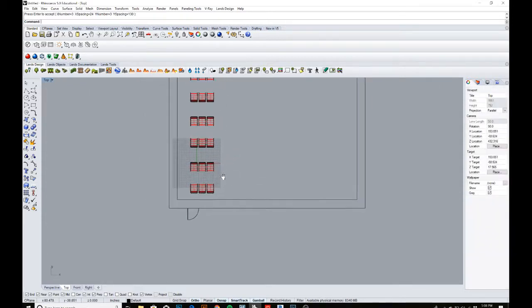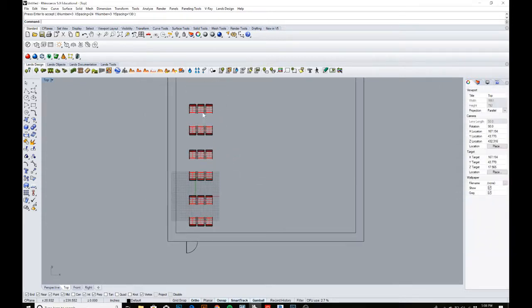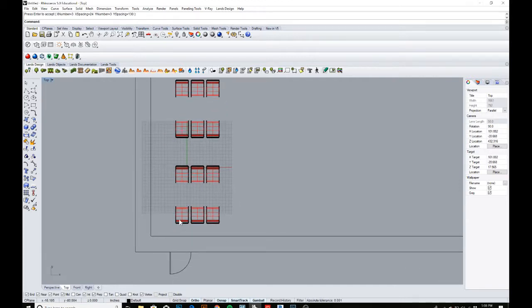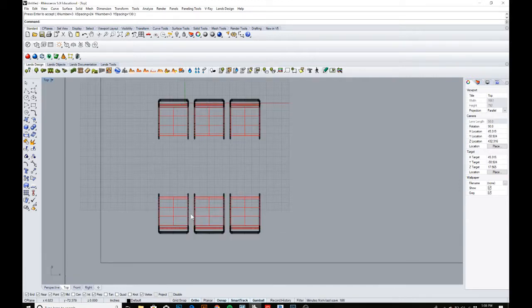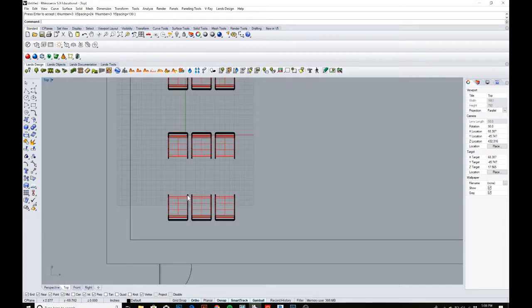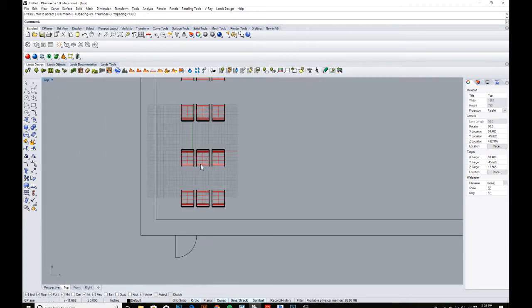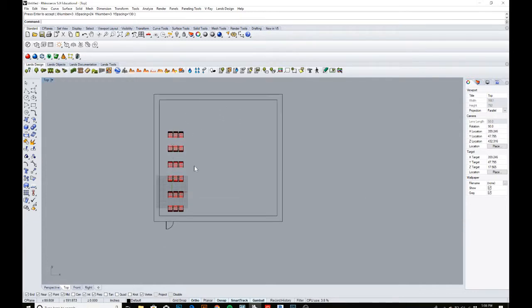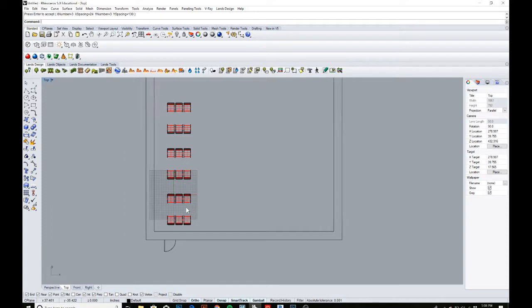So we have these groups. There's little tables in between. So my spacing on that again was from the origin was 24. That's the spacing between chairs in this direction was 24 inches, and then in the Y direction I did 130. We want a little bit of room up here for some chairs we're gonna add. So this is actually pretty good.